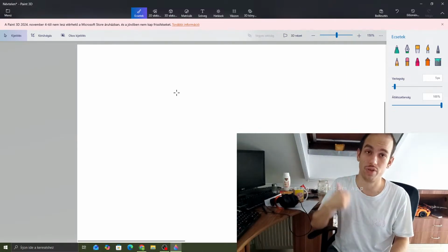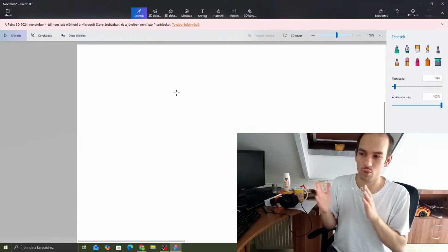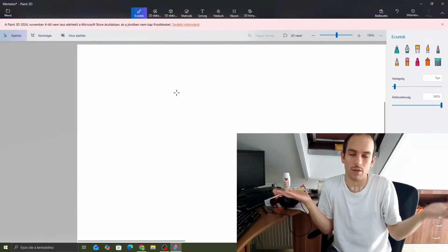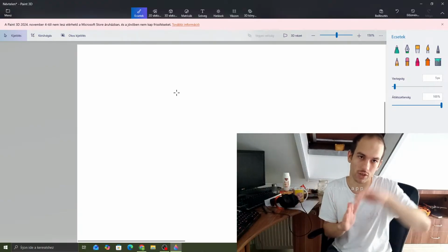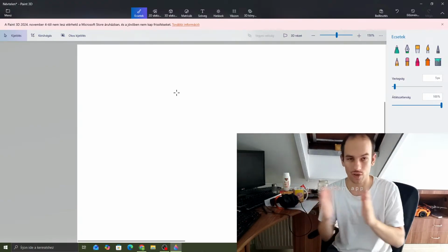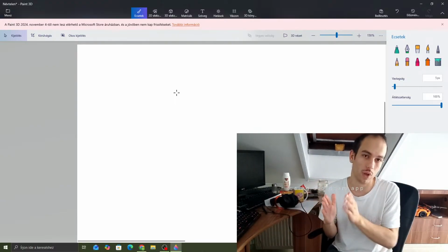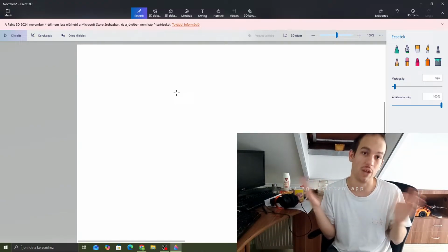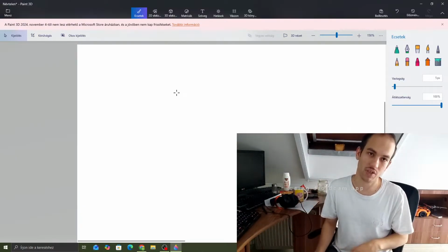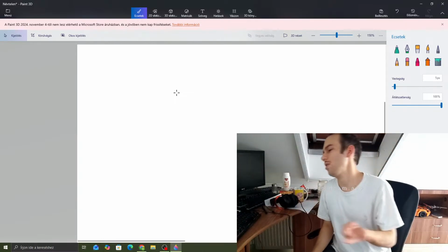The sample rate needs to be increased or the sample time needs to decrease, so that we can actually see the response, because if it is that steep, we can't determine the time constants and all this kind of stuff. You really need to pull the diagram out, meaning we need to increase the frames per second, or in this instance the sampling rate per second, which is measured in hertz.